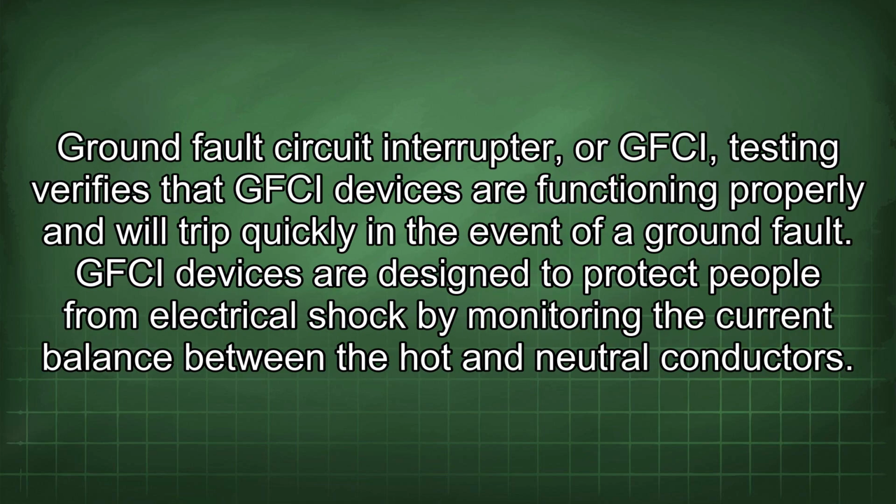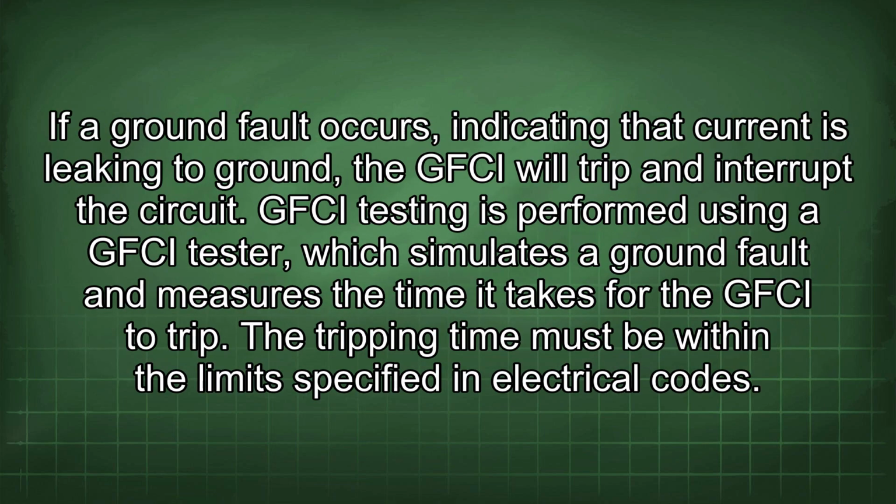Ground fault circuit interrupter, or GFCI, testing verifies that GFCI devices are functioning properly and will trip quickly in the event of a ground fault. GFCI devices are designed to protect people from electrical shock by monitoring the current balance between the hot and neutral conductors. If a ground fault occurs, indicating that current is leaking to ground, the GFCI will trip and interrupt the circuit.